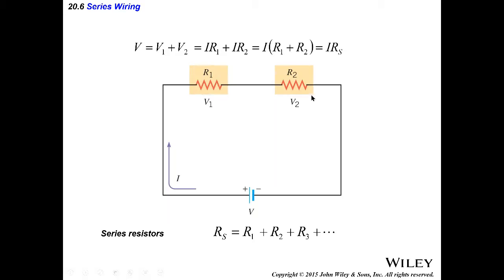Yes and no. Because if one of them broke, no current can flow. Because this one already broke. There is no current that can flow now. You got the idea? Therefore, you don't want your season lighting to be all in series. You got the point now? Because if it blew, then there's no way for the current that came here and was singing along to continue.